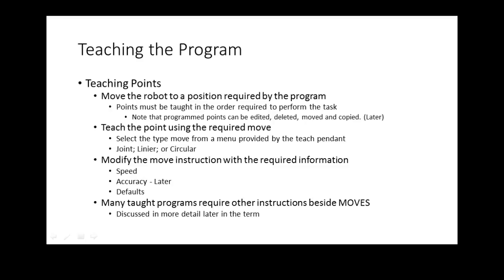So when you do a linear move, it's going to move in a straight line. When you do a joint move, it'll never move in a straight line. It'll take a path to try to get from point A to point B as fast as it possibly can. And a straight line is not necessarily the fastest path. We explained that, right? Why? A straight line is the shortest distance between 2 points, but it's not necessarily the fastest path.